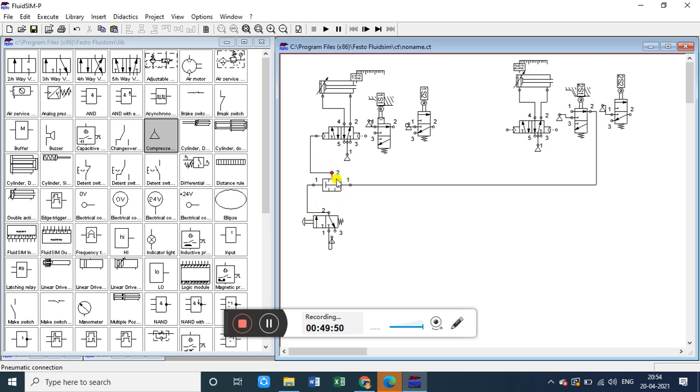When we press this, the supply will go to this side. It will actuate this and take the piston to the right hand side. That means it will come to 1s2. 1s2 will get pressed, and the output from 1s2 will help to get B plus. How to get B plus? By supplying compressed air from the left side line, we can get B plus, or extension of the cylinder. That means by giving supply on the left hand side of this valve, you can get B plus. B plus means this rod end will come to the 2s2 position, the piston will come to the extreme right side.